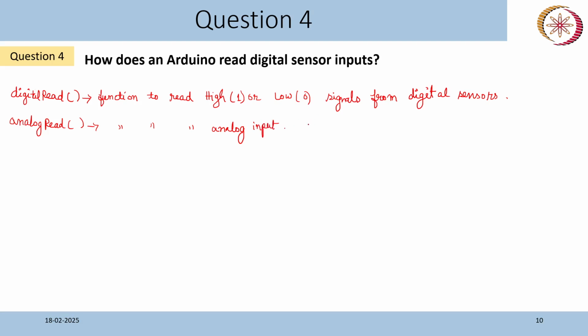Okay, so what it does is provide your input. It will give you input, but how will it give it? It will return a value. In the serial monitor you can see the value. It returns a value in the range 0 to 1023. Okay, so basically there are 1024 values, and between those 1024 values, one value will be returned.